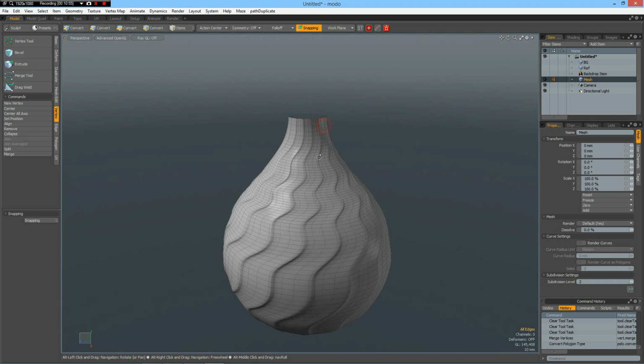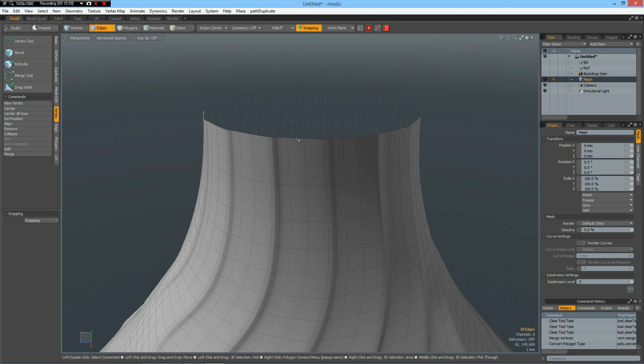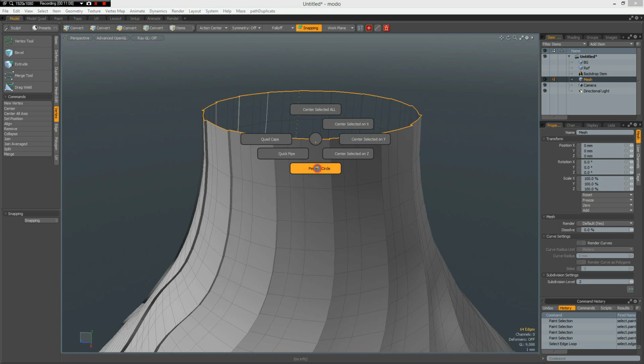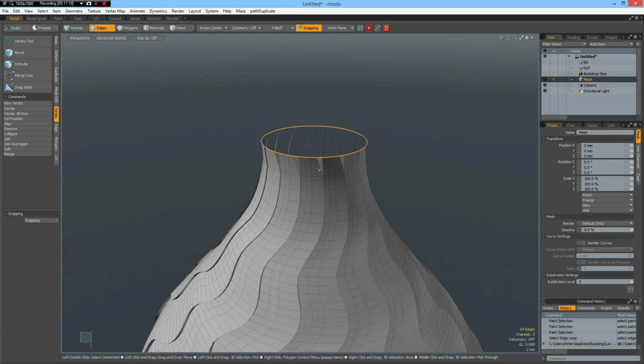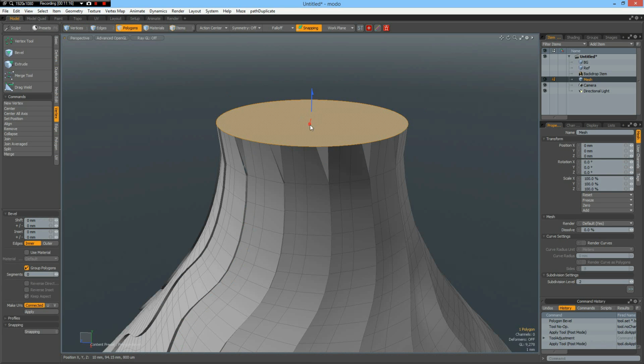It's now just a few little things, like we make the top. So I select this, go out of subD mode, select this, run Seneca Menard's perfect circle, P key for polygon, 3 to select this polygon, B for bevel, on the red handle bevel it in, shift click, bevel it down and delete.